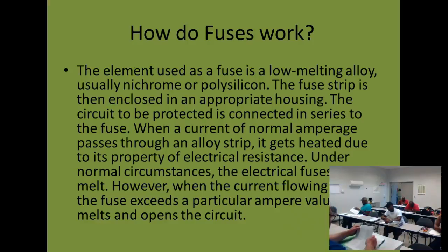Instant blow or fast-acting type fuses are sometimes used as main fuses, because they will not carry current above their rating, which is in amps, for any length of time. They must be sized to carry the maximum starting current of the unit. This starting current could be more than 150% of the operating current.